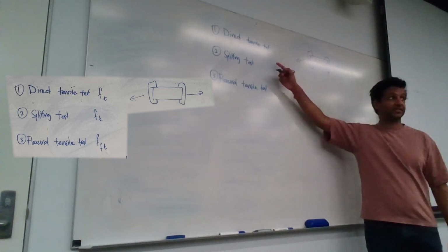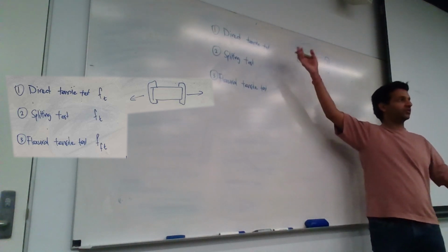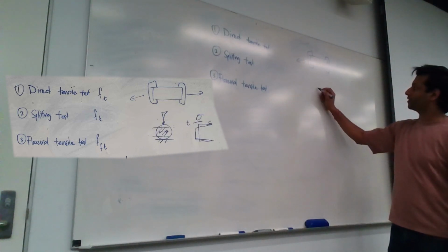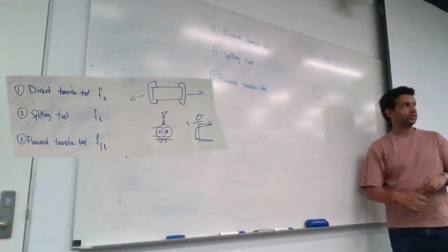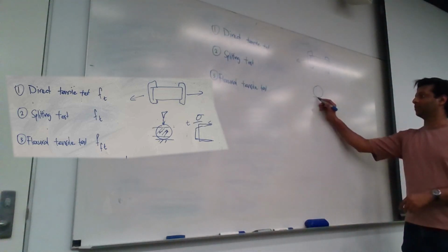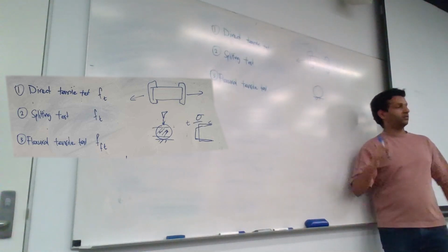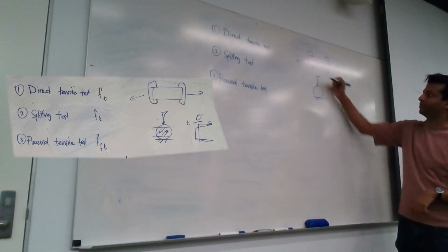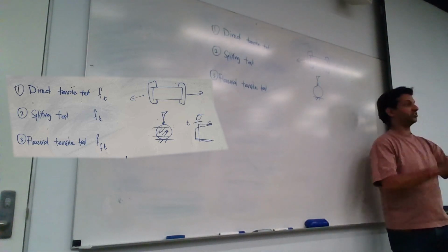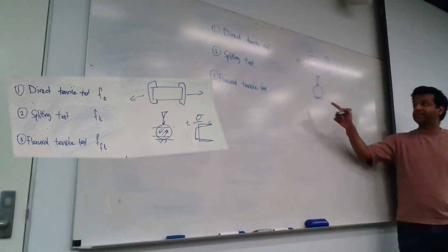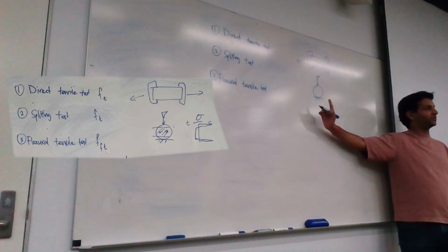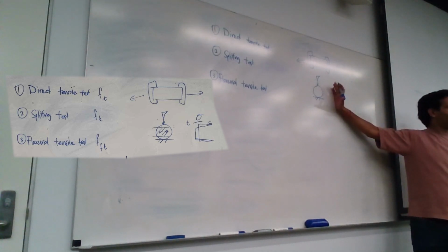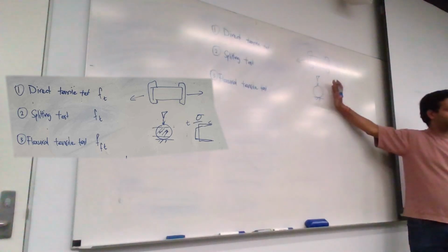Okay, that's the direct tensile test, but it'll give you the tensile strength of concrete directly. The splitting test is where you've got a cylinder that's lying on the ground, like that, right? So imagine this poking out of the board, and you've got a blade on top that's smashed through it, and you cause it to split. This is counterintuitive because people will say, wait, hang on, you're putting the concrete cylinder under compression, right? How does this give me the tensile strength?